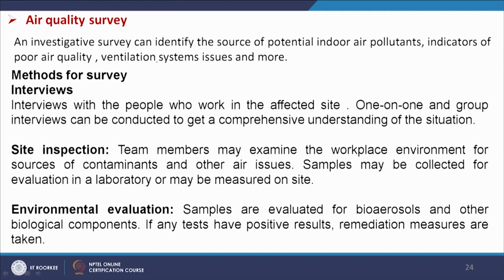A survey is necessary to understand the air quality, whether indoor air or outdoor air. An investigative survey can identify the source of potential indoor air pollutants, indicators of poor air quality, ventilation system issues and more. The methods for an indoor air quality survey are interviews, site inspection and environmental evaluation.